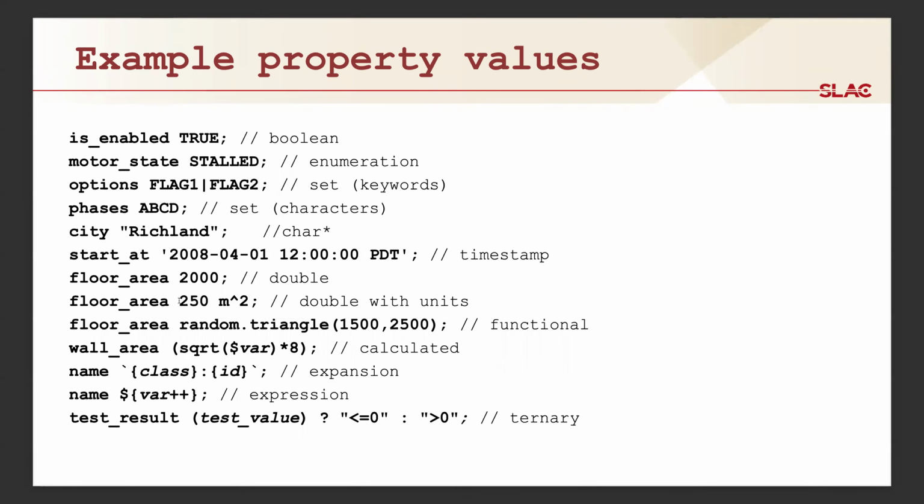Here, setting the floor area to 250 square meters allows you to be certain that you're getting the right area, particularly because you may not be certain what the floor area is stored as internally, and providing 250 might not work. In fact, it wouldn't work the way you expect because usually floor area in the house module in particular is stored in square feet. Providing the unit ensures automatic unit conversion and correct handling of the value that you provided.